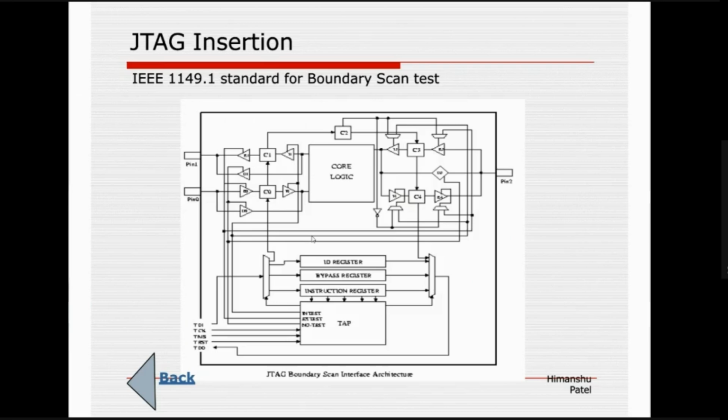If there is no JTAG, the internal components are this BIST, MBIST or LBIST or scan, anything for that sake. If you don't have JTAG at the top of the SOC, at SOC level, considering this is a full chip SOC, and you have multiple blocks inside, CPU, GPU, display and so on, then it will be at the top.